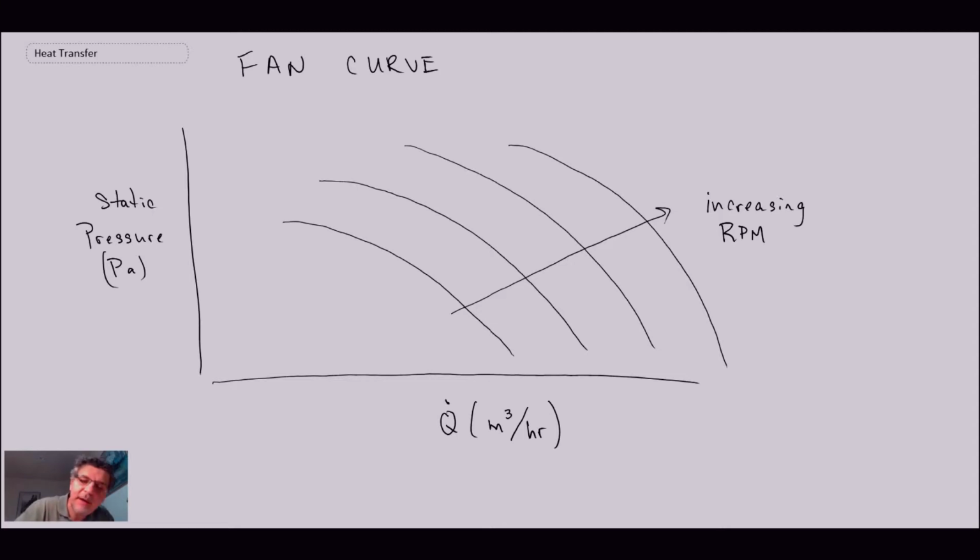Typically in the video that we just saw, the fans were being driven by an AC motor. Depending upon where you are, it depends on the power grid. If you have 60 hertz power, typically that gives us 3600, or 3560 is sometimes what is used to allow for slippage. But 3560 RPM, you wouldn't want these fans spinning at that high of a rotational rate.